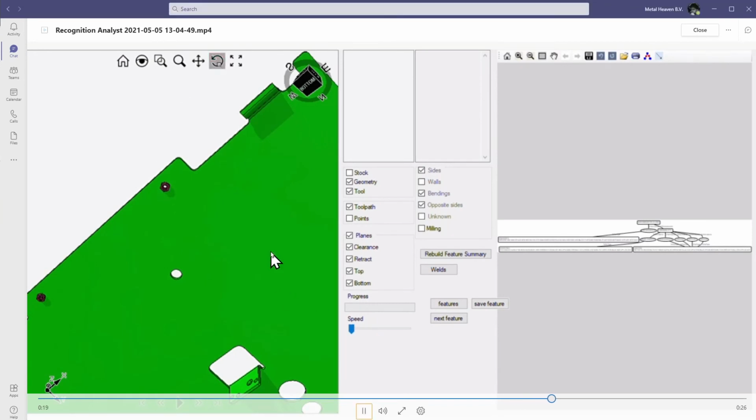What you see here is another assembly which has welding nuts. We select a welding nut, and then you see that also the sheet plate is highlighted, showing that with the welding nuts as well, through collision detection, we are able to detect which sheet it is connected with. So independent of how the engineer draws this, and if he applies the correct hierarchical structure in the sub-assembly structure, we know through collision detection what is connected with what. And we will use that for the whole estimation. So that's where we are right now.